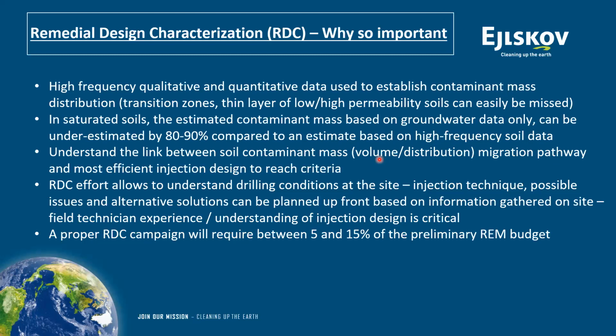So we like to go into saturated soil and try to collect as much soil data as possible, because we can see that you can easily underestimate by 80 to 90% your mass estimation just by looking at groundwater data instead of soil data in the saturated layers.